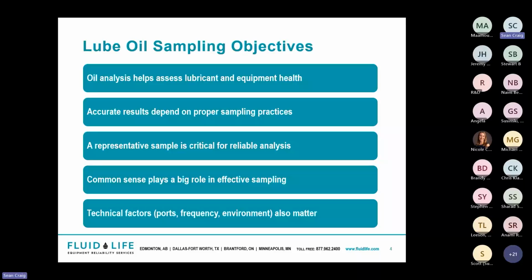With that one sample, you can first get a good view of the health of your oil and component, and then narrow it down to one of the two. But obviously, to get that good sample, it all starts with proper sampling. A good sample will give you accurate data.